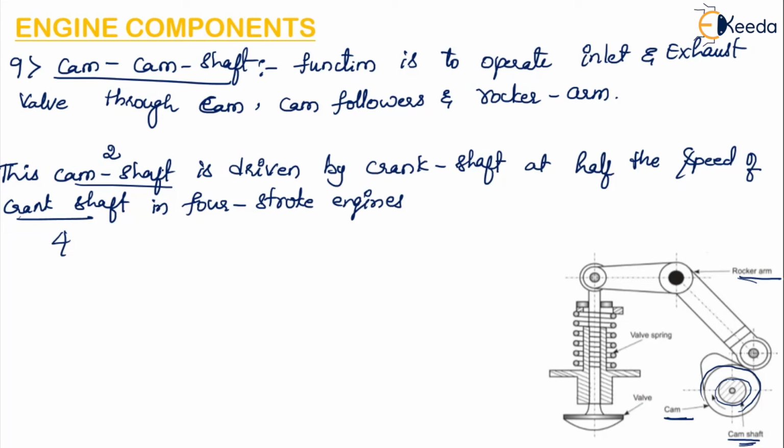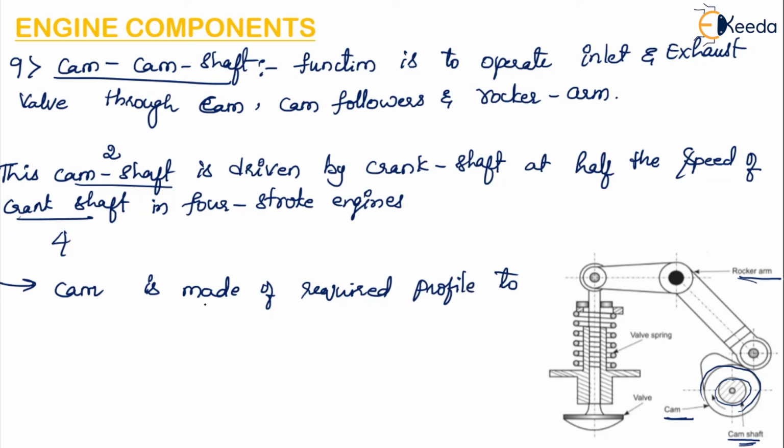The cam is made of the required profile to give the desired motion to the valve. A cam can be made with a circular profile, or elliptical or oval, based on the type of motion we require for the valve.